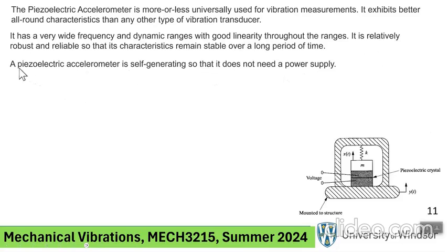They do not need a power supply because the squishing of that piezoelectric material will create a voltage. Remember, in that generic and old-fashioned accelerometer, you had to attach it to a power supply because it was based on the voltage divider formula, so you need a power source.